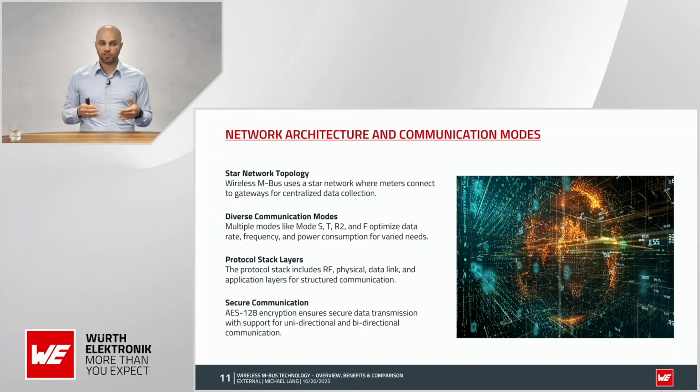The third point: there is a protocol stack layer integrated into wireless M-Bus, and it includes the complete RF and physical data link, so all layers are integrated in this wireless M-Bus communication. And last but not least, and I mention it again because it is very important, you have a secure communication, as this is sensitive data in the end, or could be.